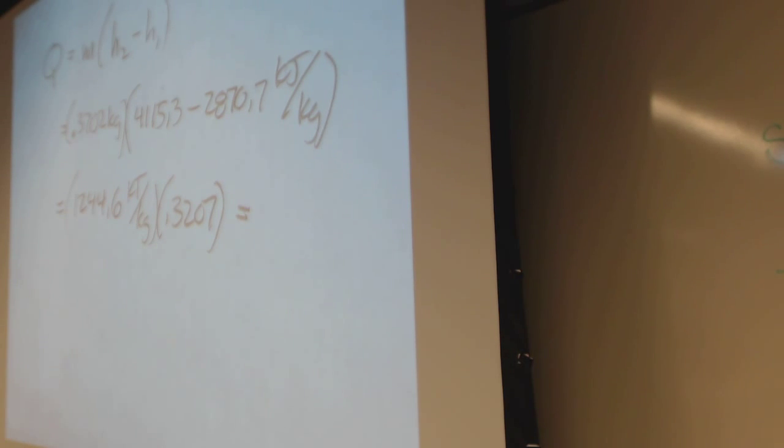Did something move to get bigger? The piston moved, right, from a certain size to another size. There was a spring holding it down. What do we know? We know the pressure changed. We know that it's a linear spring. Don't know the K factor for the spring. Don't know the area of the piston, but they gave us volume, so we're going to use that.